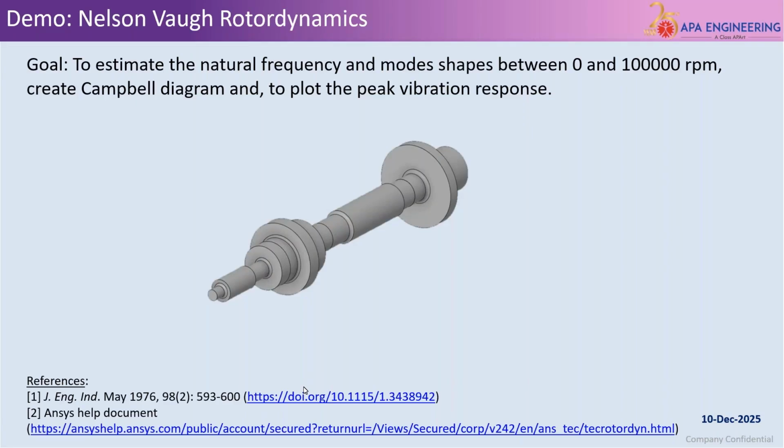We will jump on to Ansys to see the demo session. Our goal here is to find the natural frequencies and mode shapes between 0 and 100,000 RPM. We will create a Campbell diagram, and plot the peak vibration response in terms of displacement. We will also plot an orbit plot. I will jump over to Ansys.